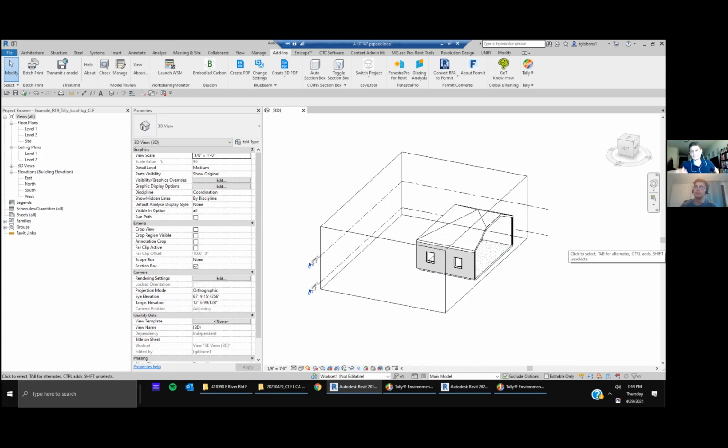As far as model setup, having been in Revit for so long and feeling like I understand what it wants, which is kind of scary sometimes, Tally's pretty turnkey. Once you install it, it essentially just pops up in your add-ins. And that's kind of it. Then you really just press the button and it walks you through the process. I think the only big question for me that comes up a lot is sort of to detach or not to detach, which is often the question.